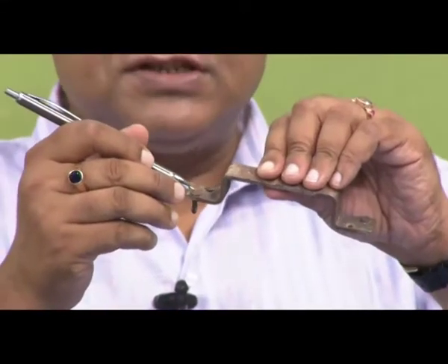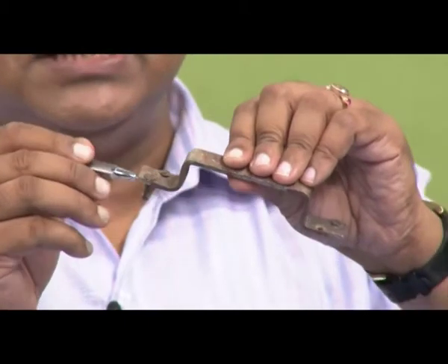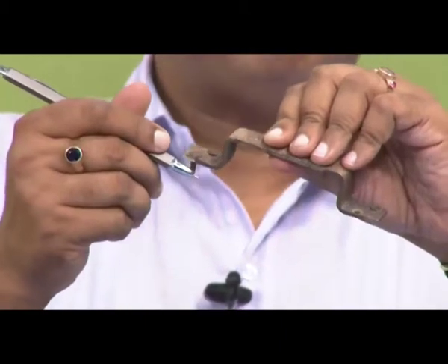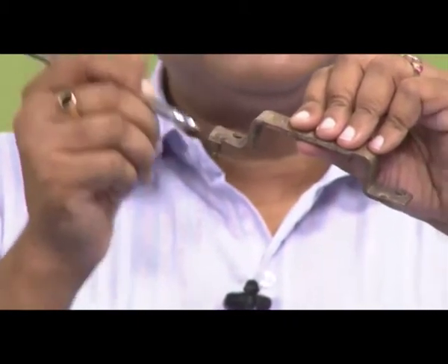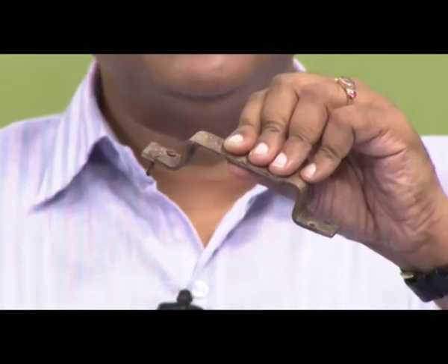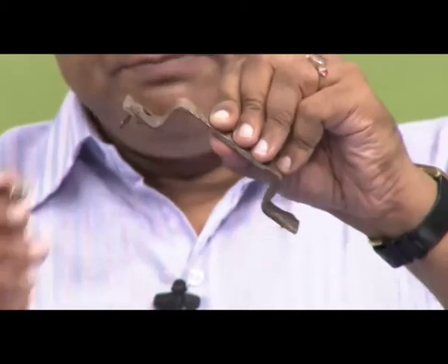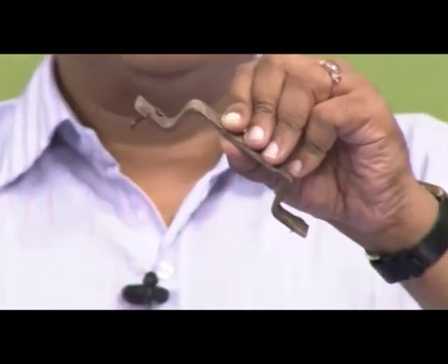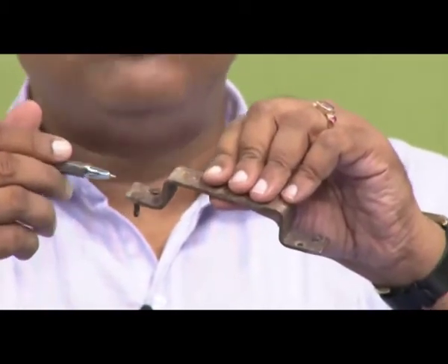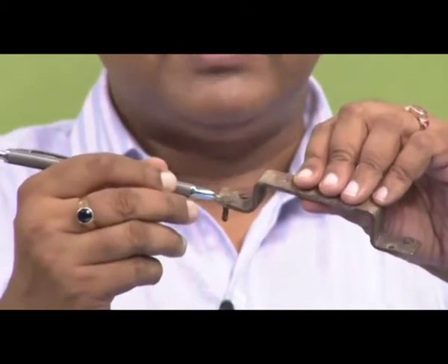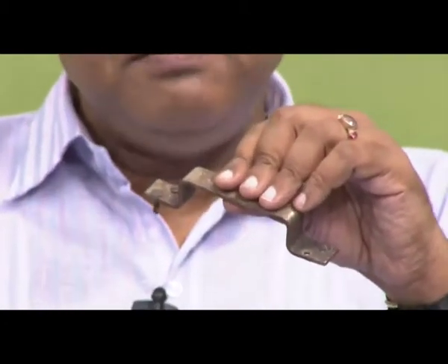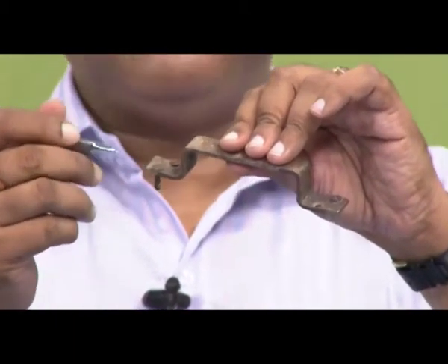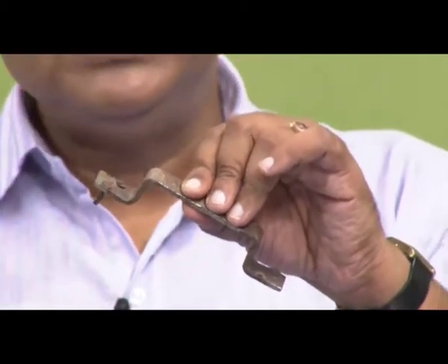At the same time we have oxygen here, but the oxygen content in this zone will be very less. So, here we have a maximum oxygen, but as we go towards depth, the oxygen content would reduce drastically. So, that means this zone at the extreme part would be anode, but the top part where we have more oxygen, the cathodic reaction, which is oxygen reduction in neutral media.